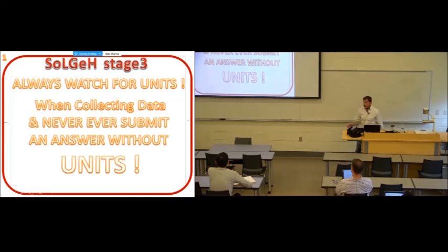Finally, stage 3, and this is where I found 80% of problems in engineering come from: units, compatibility of units. Once you have the output, check, is it logical? Are the units compatible? Even in the software, you may enter the moment in ton meter and the pressure in megapascal, and then the whole scenario is messed up.